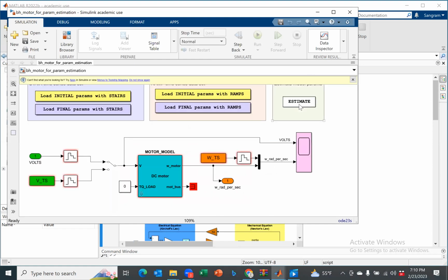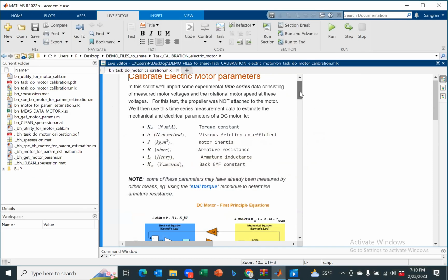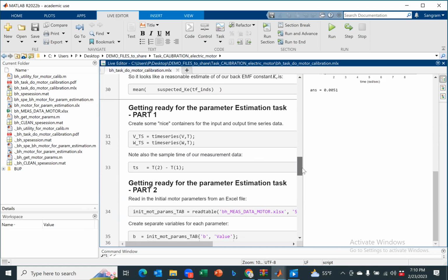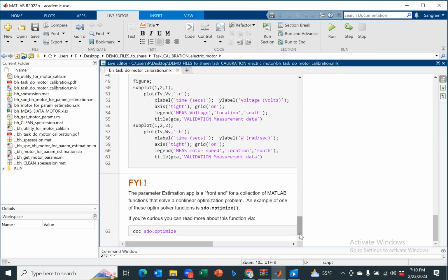And then whenever you use a motor, what you need to do is you need to do the parameter estimation. So you can do that. And then you can provide certain control input to the motor, see the response of the motor, and then come up with the inertia properties, the damping properties of the motor. I would encourage you to read through this. If you have taken, or if you are taking EGR 550 mechatronics systems, Professor Sugar teaches the exact same thing.